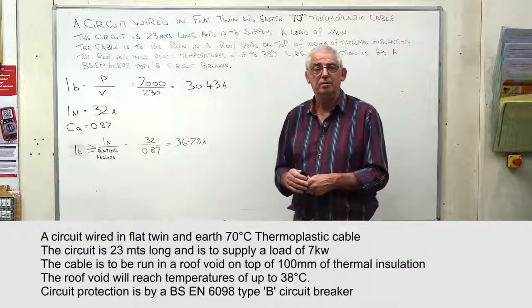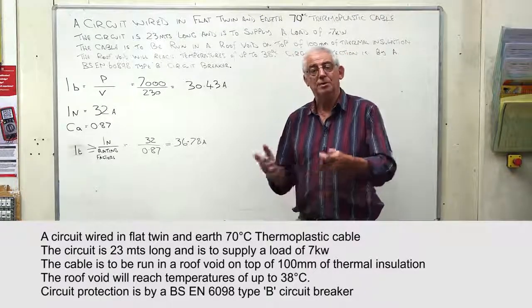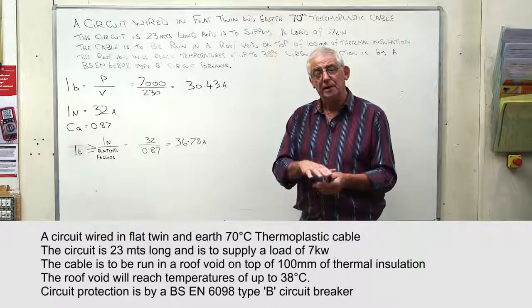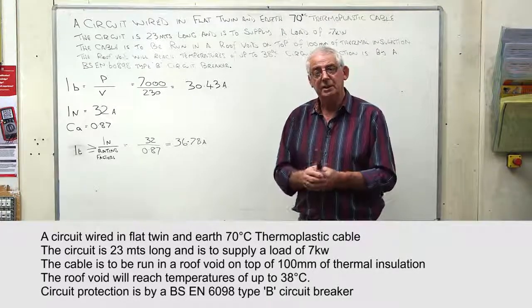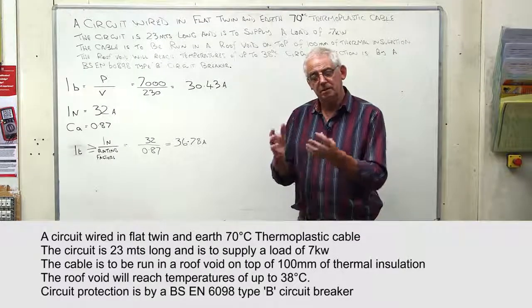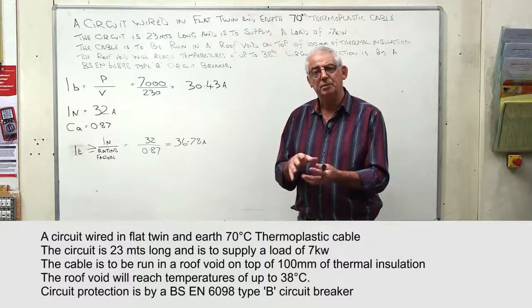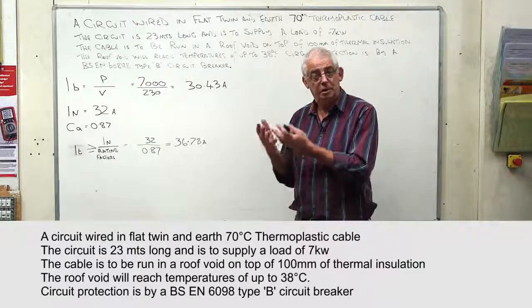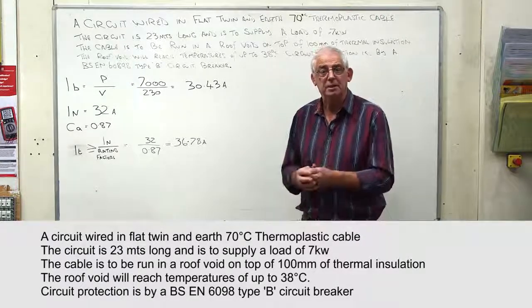So we know that if we divide or multiply anything by 1, we're going to end up with the same value. So 30 degrees is the norm. Anything above that, we need to calculate for. And it's going to make us choose a bigger cable, because when current flows through a cable, the cable warms up. It's just a natural occurrence.